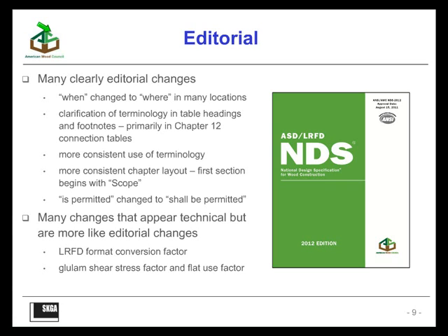Now there are also many changes that are actually quite extensive and cover many paragraphs and clauses that appear technical, but they're not purely editorial changes, but they're like editorial changes. These include cases where we have the LRFD format conversion factor. I'll get into that a little bit later. And glue-lam shear stress factor and flat use factors.